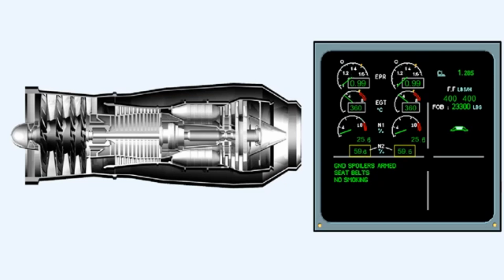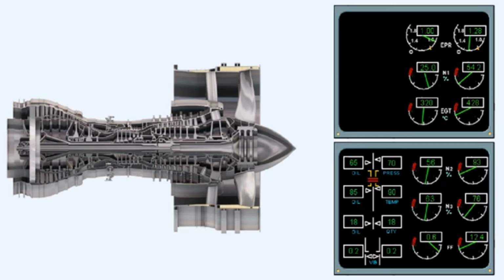The ground-idle HP RPM of a twin-spool engine is in the order of 58 to 62%, and the LP RPM idles on the ground at about 25%. In flight, these idle values will be higher because of the windmilling effect caused by the forward airspeed. In a high bypass ratio turbofan engine which is running at an idle power setting, the fan speed, or N1, is 25% of its maximum value. The engine will generate approximately 5% of takeoff thrust at this power setting.